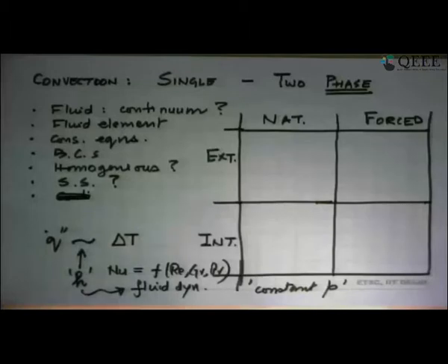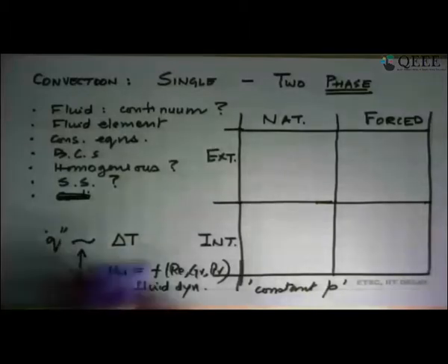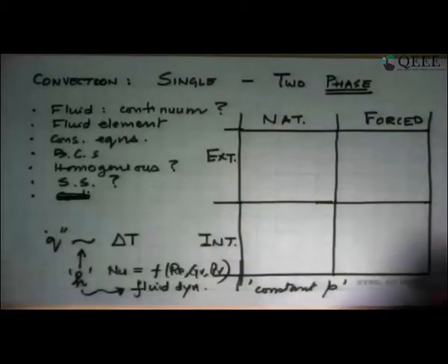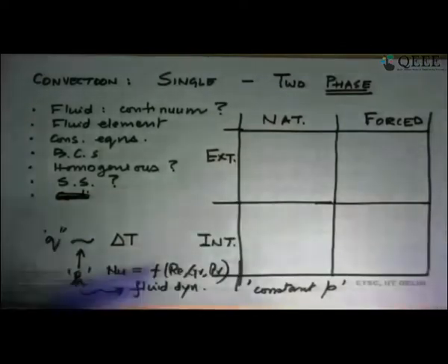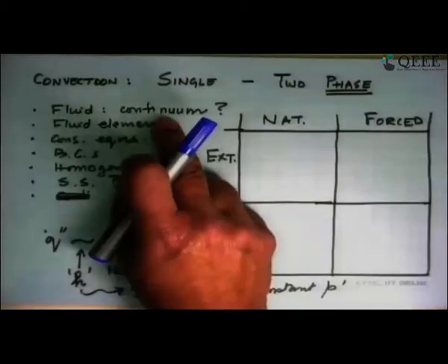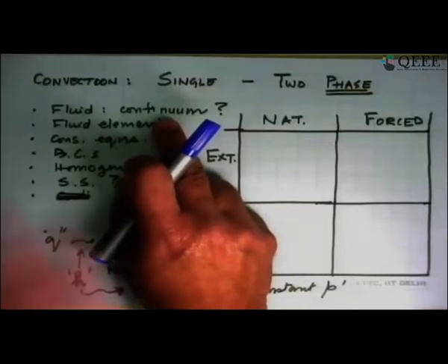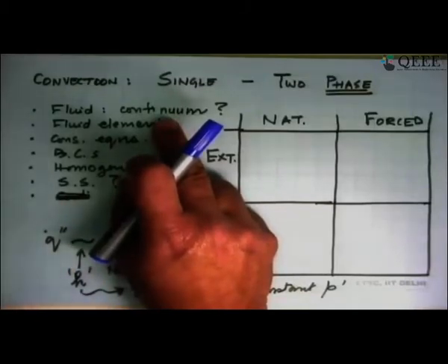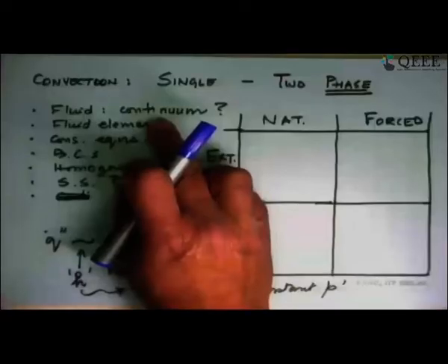So the first thing that happens in the case of boiling heat transfer, and condensation as well, is that there are some very fundamental differences in the whole approach. And I've listed some of these points over here. What it tells us is that in single phase flow, we had only a single fluid, which is like a continuum. Everywhere it was homogeneous, it was in the same phase, and we could consider it as one particular substance. But that doesn't happen when you have phase change.